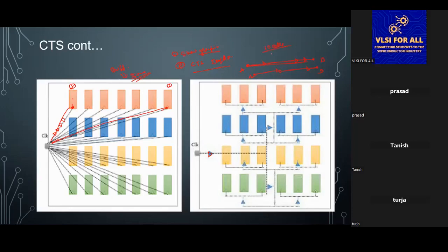If I want to do it manually, I need to go to this location and do some steps. We have to do create cell, insert cell, add buffer on route. Two commands will be there. I have to go here and put one cell like this. Manually, it will take 1 hour. If I have some scripts, I can add the cells in a single shot, right?